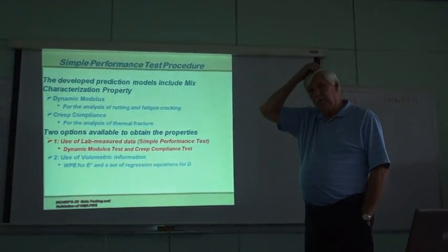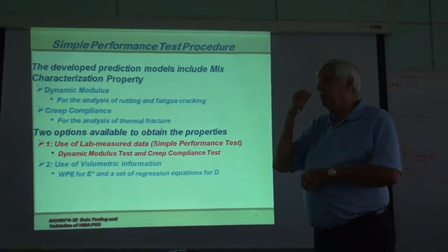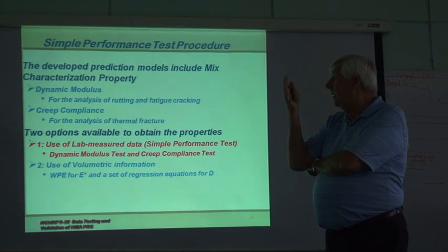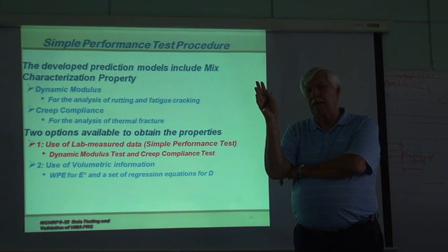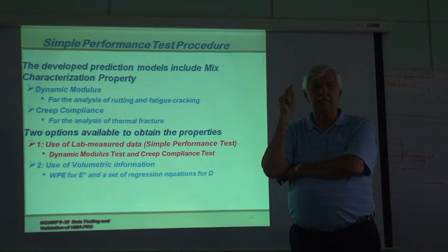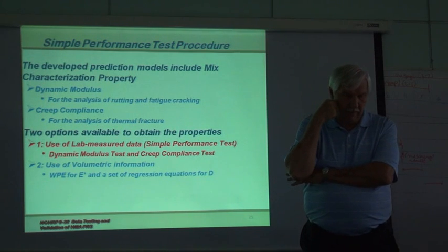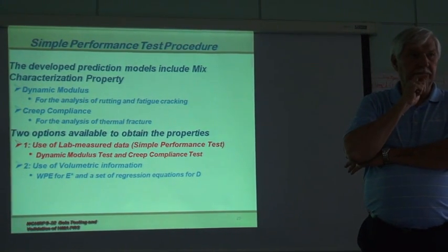Okay, this is the important slide. It kind of tells you here, now let's get into the simple performance test procedure. And if we look at the prediction models, trust me, what you have is the most important simple pavement performance test that we found, and what this is based on is the E star of your asphalt mix.